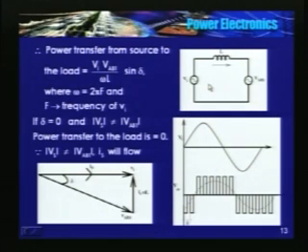Now what if I make delta equal to 0? In ideal condition, consider my inverter is lossless, and I have a capacitor at the output. If I make delta equal to 0, the power expression says that power transferred from the source to the load is 0. So therefore definitely there has to be no load in the output. I have neglected the losses in the converter.